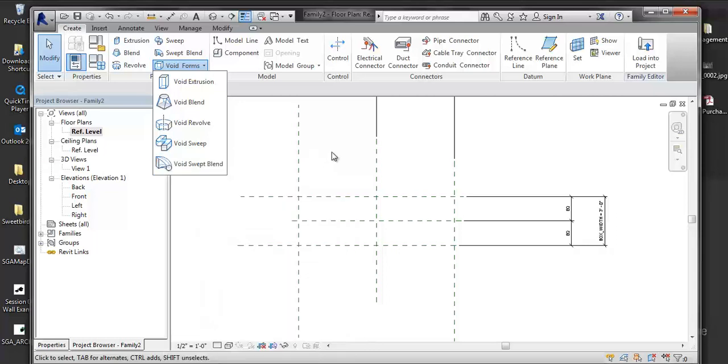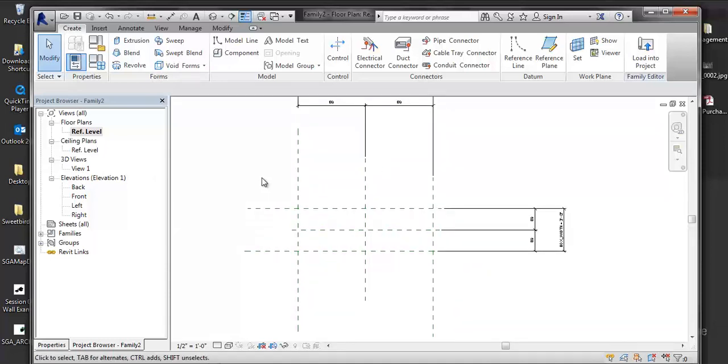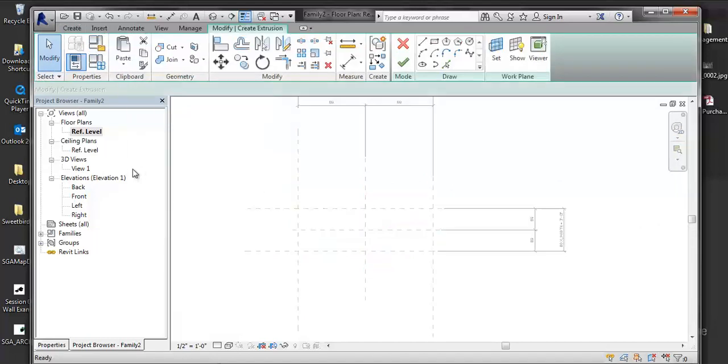Cool. Make sense? So in this office, most of the stuff you're going to do in Revit is probably not so much extrusions. You'll be doing a lot more creativity and also needing to use Rhino for a lot of things. Extrusion is all we need at this point. I'm going to click on extrusion. I enter into my sketch mode, similar to the way I edit a profile on a wall or make a new floor. I'm always entering into a sketch command and then saying what I want. So you're going to have to follow along well with me.